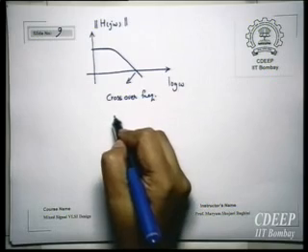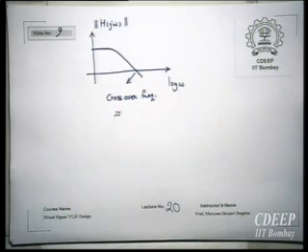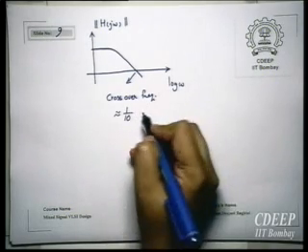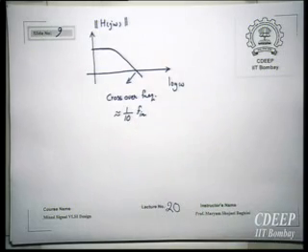Usually this we want not to be very large. We want to limit this frequency. Usually this is chosen almost around 1/10 of the input frequency. Suppose you have an input frequency of, for example, 1 gigahertz with a divider of 16. 1 gigahertz upon 16 will be how much? 1 upon 8 is 125 megahertz, so it will be around 60 megahertz. 1/10 of 60 megahertz will be 6 megahertz, right?